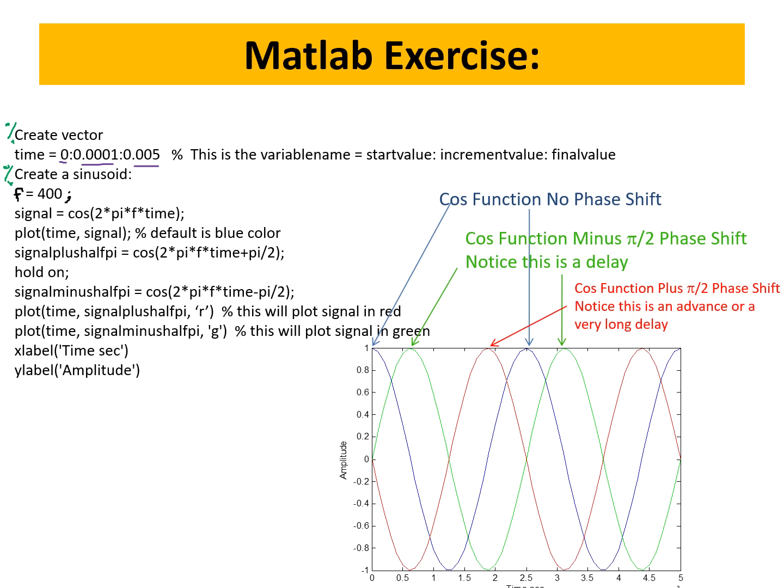Now, your frequency is 400, which means what is your period T? It is 1 over 400, the period in which the sinusoid will repeat itself. So we're good with that. Now we would like to look at three things: a signal without shift, a signal with a negative phase shift, and one with a positive phase shift.